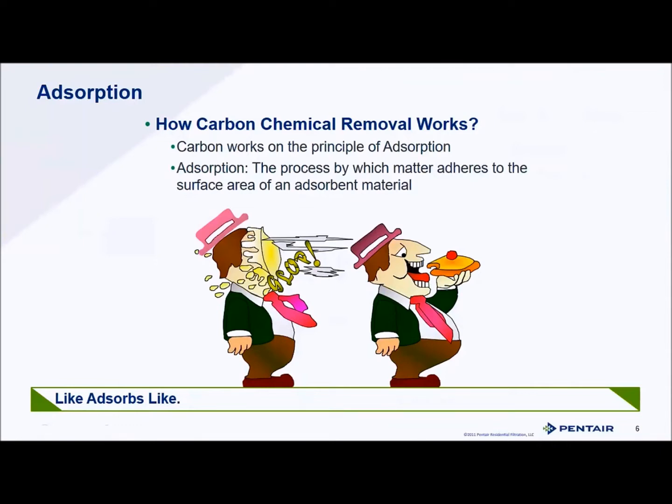There's a spot where they mix in between, a thin layer there, but the majority of stuff is pushed up against, into a separation layer. That's what's happening with activated carbon. We're giving a layer for those organics to plate out on or coat out on in mid-water stream to remove them from the scenario. And they stay adsorbed to the surface of the carbon.